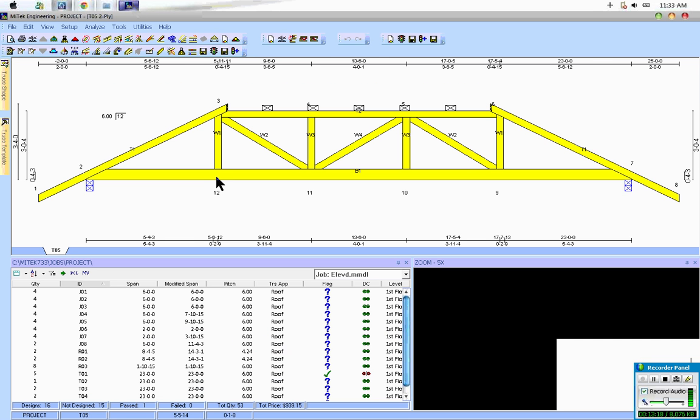One thing I think I failed to point out is not only does it give you the quantity-sensitive trusses to each specific elevation, but you can come into the folder for that entire project, and that will list every single truss in the job, whether it's on the A, the B, the C, the D elevation, and it will put everything at a single quantity. Since the quantity is different from elevation to elevation, you can use this right here to send off the entire project for seals and get a single quantity that everything comes back. That way you're not worried about specific quantities when you're sending off the seals or having to send off the same truss multiple times for each different elevation. Send everything at one time, and get it all back, and then be ready to go.